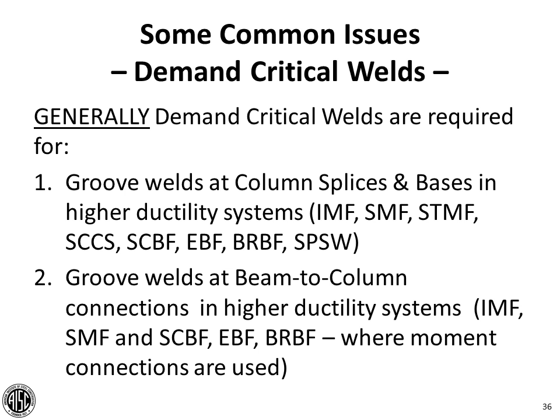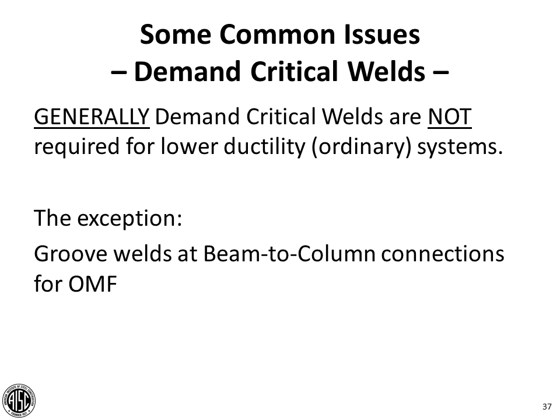Now it may seem odd to talk about beam to column moment connections in those braced systems, but there are options which would allow you to choose to use a moment connection to satisfy some of the requirements of those systems. And when that happens in these higher ductility systems, you're going to need demand critical welds. Generally, demand critical welds are not required for lower ductility or ordinary systems. So they're not required in ordinary braced frames, for instance, or ordinary cantilever column systems.